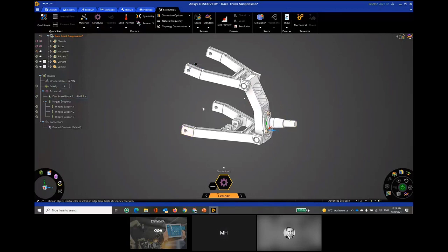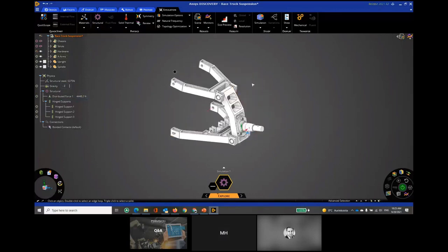Anything else? Well, at the very moment, what do we have in here is the constraints done, forces done. We do have a material which by default is structural steel, and we do also have a gravity in here, which by the way is totally the wrong direction. Let's go for negative y, and now it seems to be a bit more in place as well.